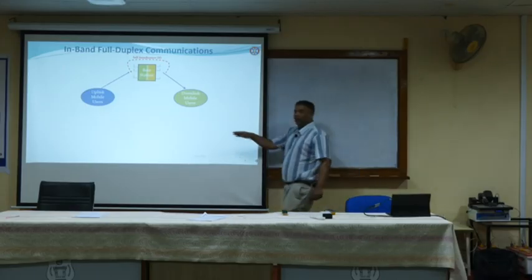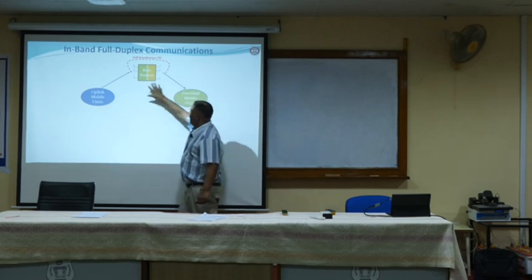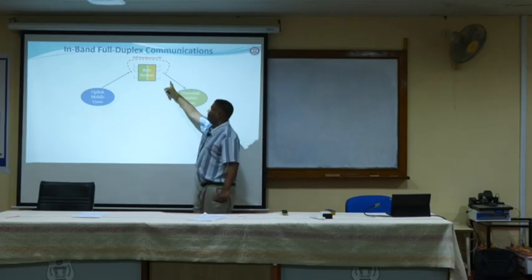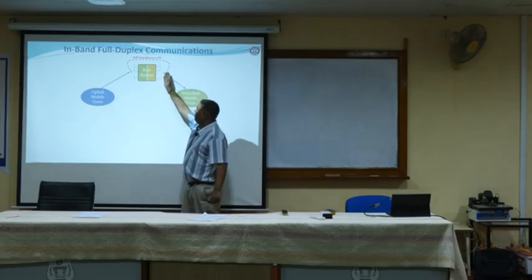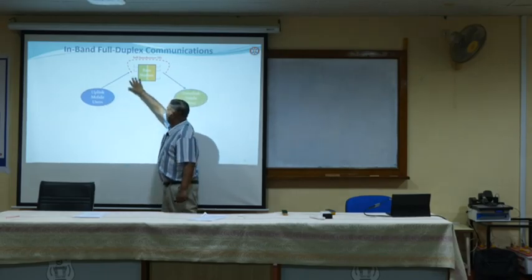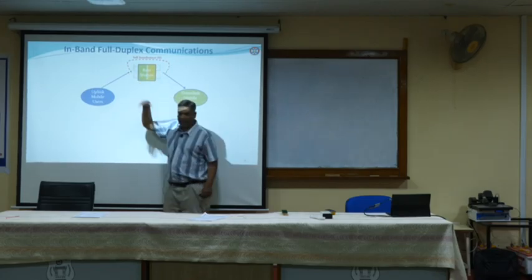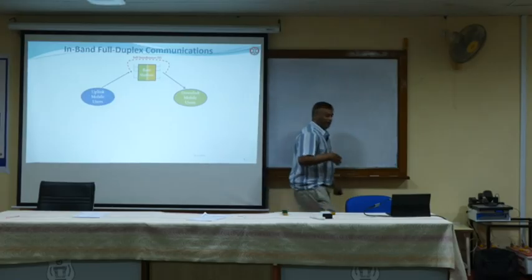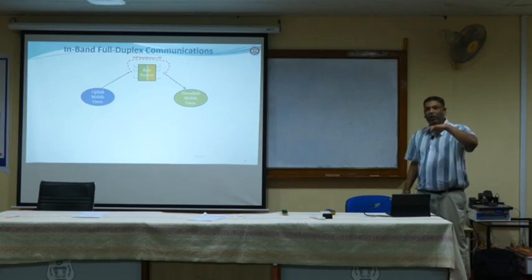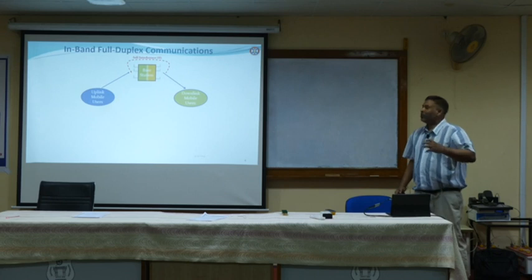So if you transmit at the same time and same frequency, and you also listen at the same time and same frequency, there is self-interference. When you transmit, you transmit at very high power to downlink users. You are also listening to the uplink users. So this transmitted signal will cause interference here because you are transmitting at the same time and same frequency. It is analogous to shouting while also trying to listen to somebody whispering. So it's like that, okay?